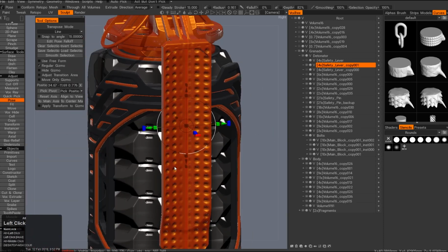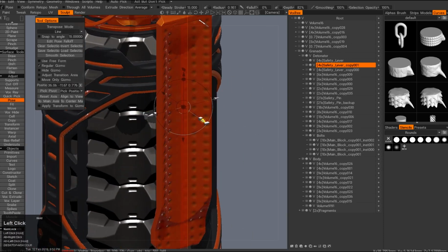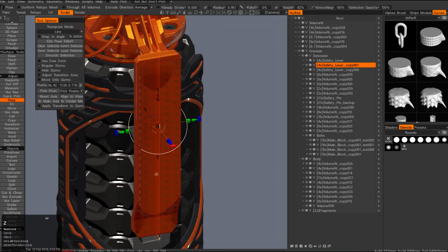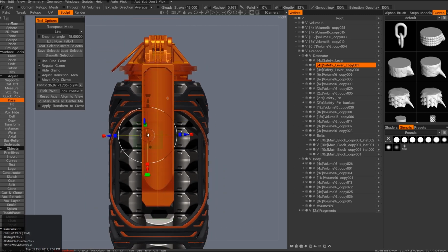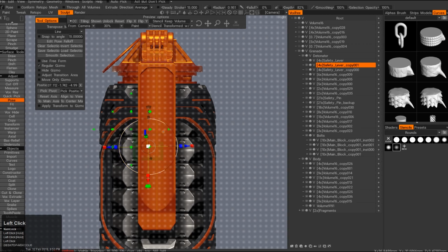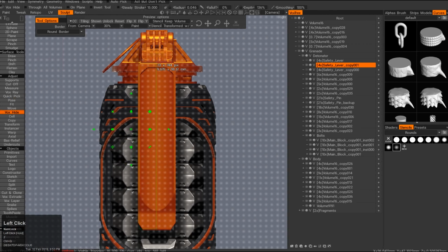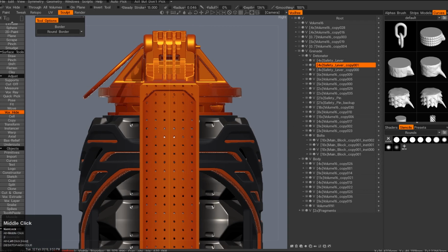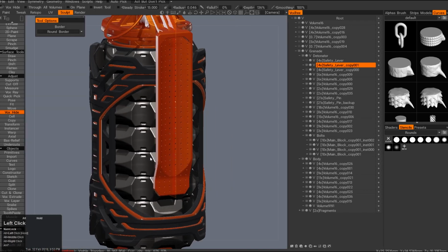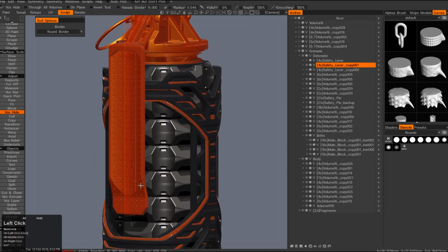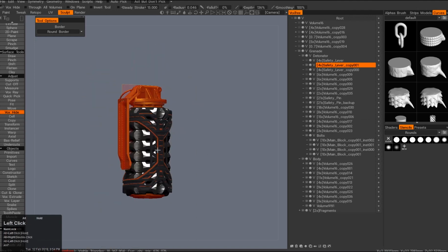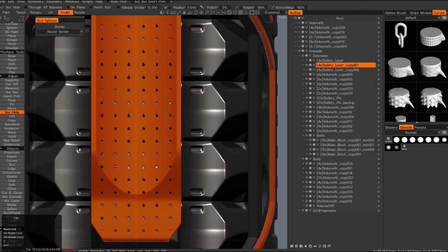And again, if you do it with the Voxel tool, okay, here actually I decided to use the pose tool and see how it looks if I decide not to make holes, but if I decide to make, well, bumps. Bumps didn't look that cool, and I decided, okay, now the holes are the holes. So I'm using Voxel, so essentially it allows me to unhide parts that I don't want to have holes on. But I also can accidentally unhide stuff that's been hidden, which is annoying. Sometimes I forget what's been hidden and what's not.